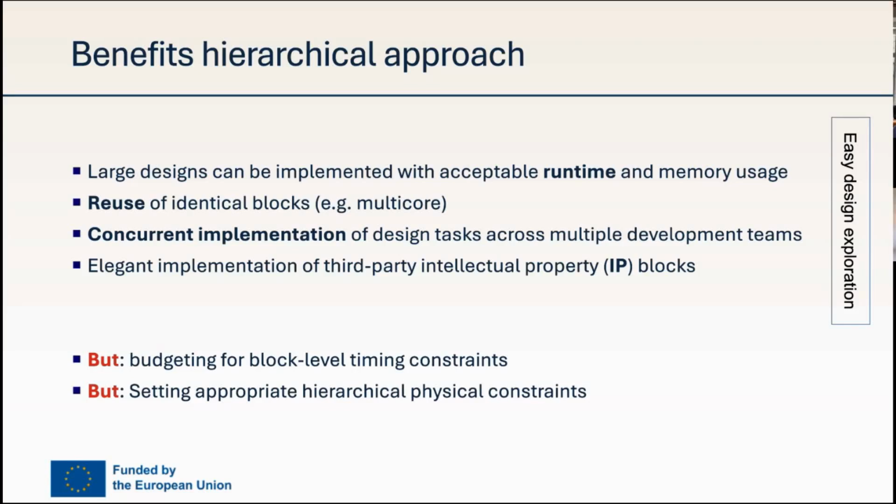Also, in a commercial environment, it is of great importance that we can work concurrently with different teams, with different persons in the same project. So maybe we have some implementation in the NoC, another one in the core, and so on. And finally, another big advantage of the hierarchical methodology is that we can elegantly implement third-party intellectual property blocks.